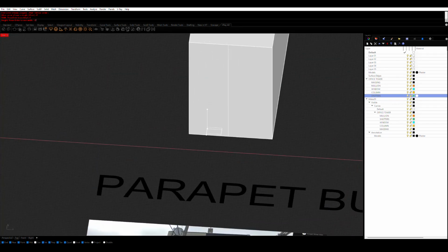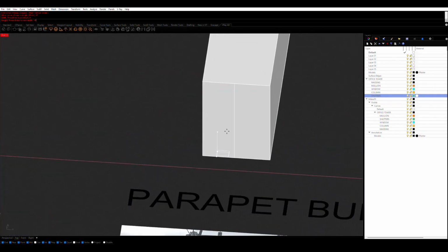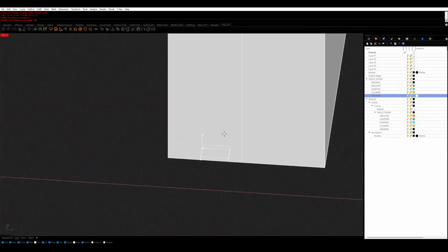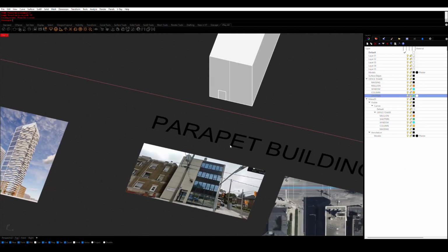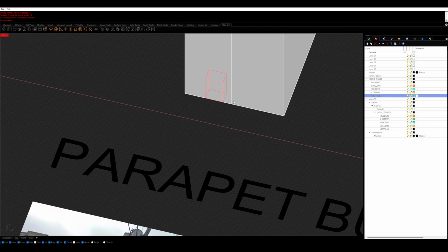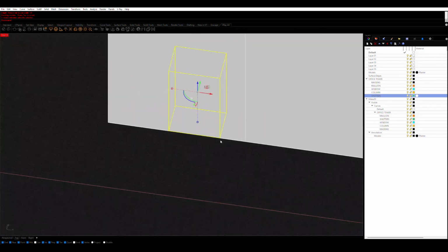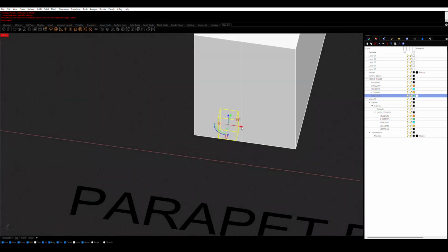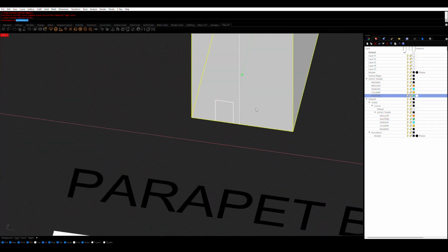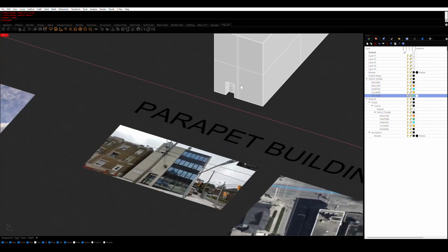And in terms of the height, it looks like it reaches very close to the ceiling, so we can go for 10 feet. That looks all right. And in terms of its offset from this center line, we can make it around 2 feet. Remove it from our massing.